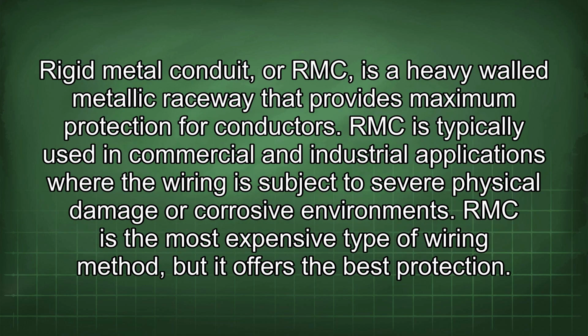Rigid metal conduit, or RMC, is a heavy-walled metallic raceway that provides maximum protection for conductors. RMC is typically used in commercial and industrial applications where the wiring is subject to severe physical damage or corrosive environments. RMC is the most expensive type of wiring method, but it offers the best protection.